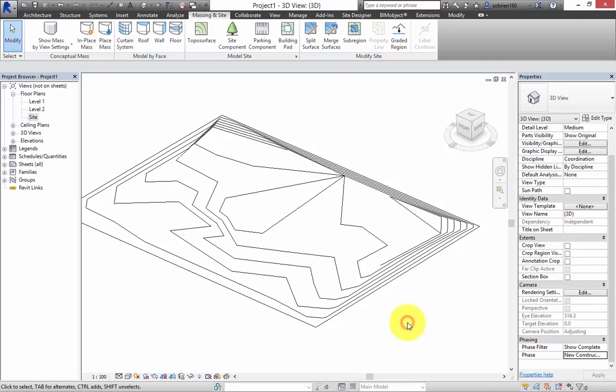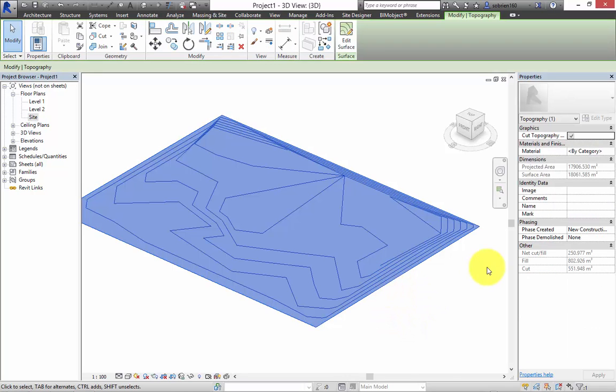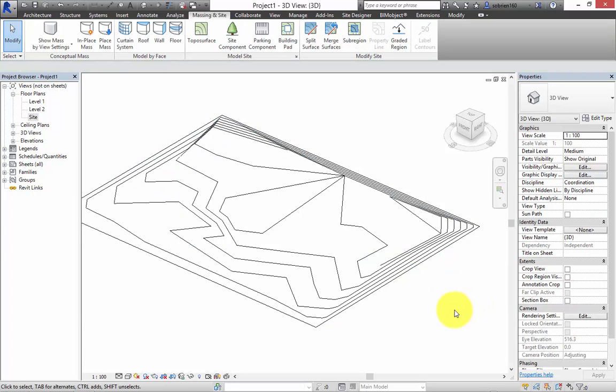All right, make sense? The benefit of that is that when I select it, Revit automatically calculates the amount of excavation and the amount of fill that is going to be required in terms of cubic meters of earth. So that gives you a specific value that you can go and calculate how much it's going to cost to do that excavation, do that landscaping. So that's the reason for doing it in reality. Make sense? Yeah. All right. So that's the first thing.